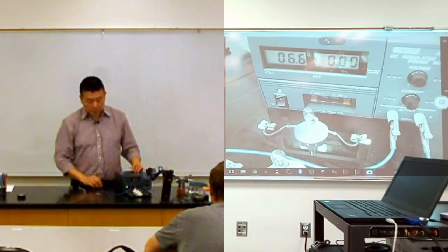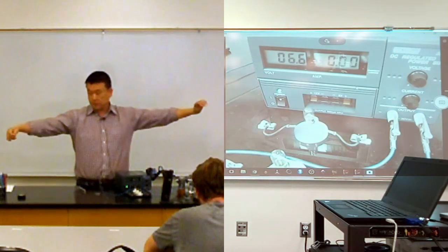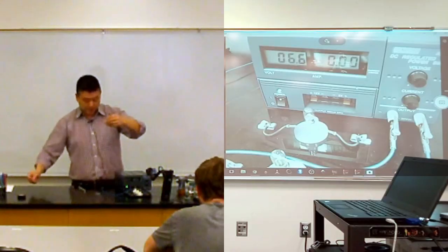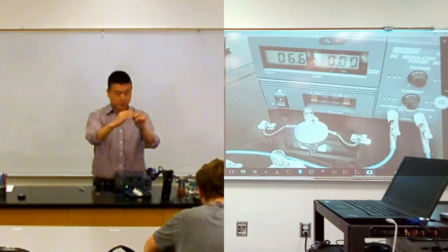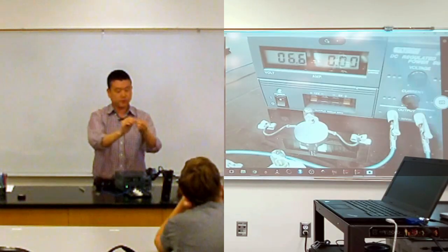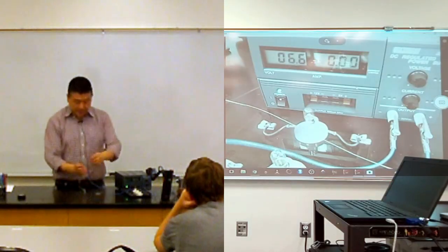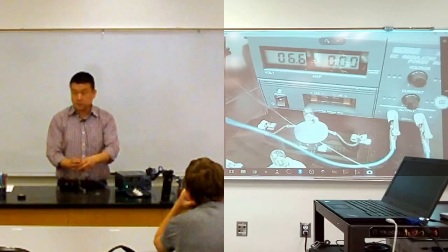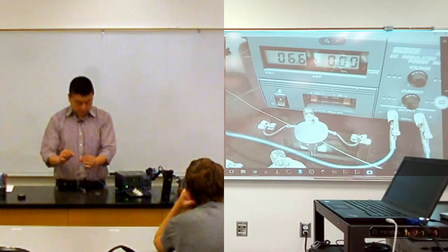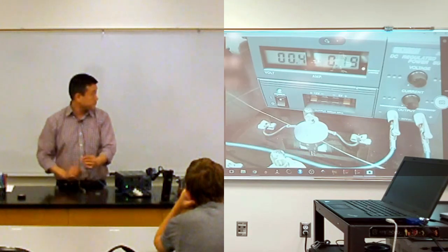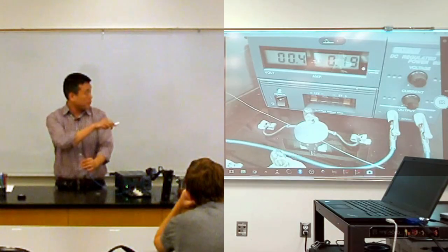But when you set up a particular arrangement, sometimes you don't see 0 volts between two ends of a conductor. So let me connect one of the wires to this end here. So the wire is connected here. Now let me wrap it around for good measure. Right now the other end is not connected, so it's reading 6 volts as you might expect. But when I connect this at this end here, oops. Now it doesn't quite read 0 volts anymore. It's reading 0.4 volts.